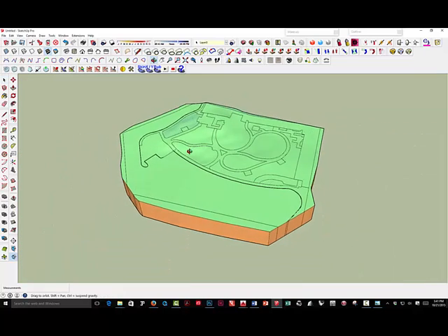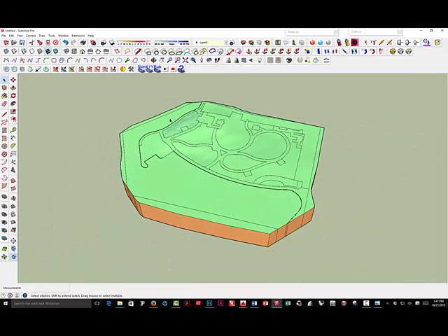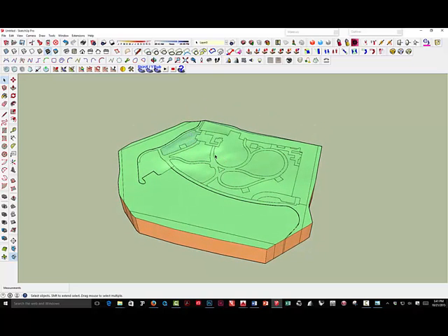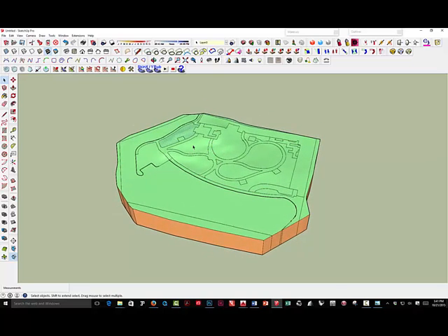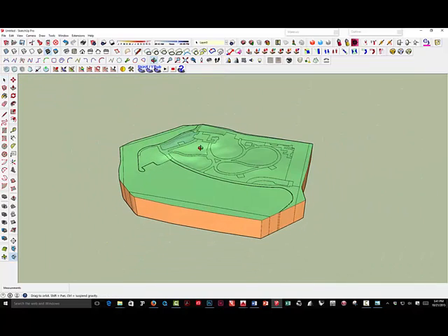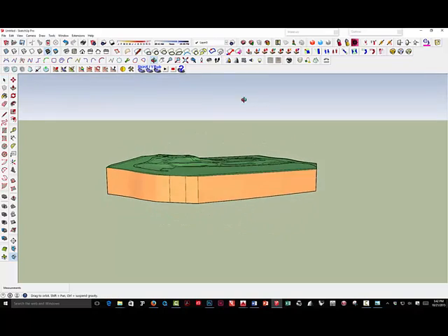So the goal for Tuesday is that you watch this video, you export these layers from AutoCAD, and then you go through this process importing them into SketchUp, turning them into two-dimensional surfaces first. You could take those and just drape them onto here, but I find it works a lot better to take a little time to close it as a 2D surface because it's simpler, and then take that surface, create the terrain model, and then drape it on the terrain model.